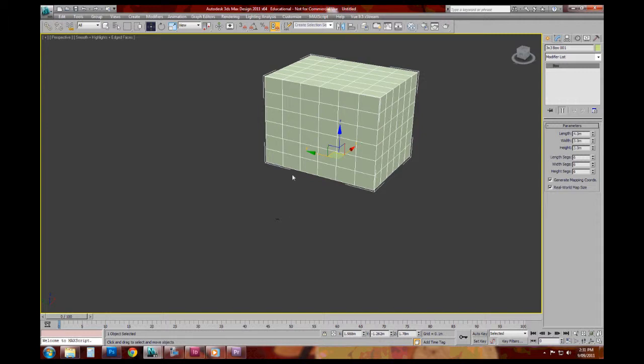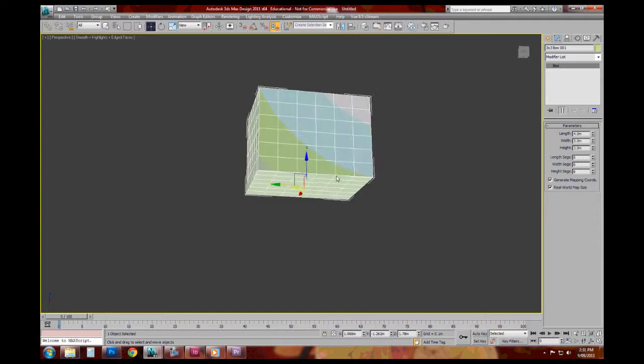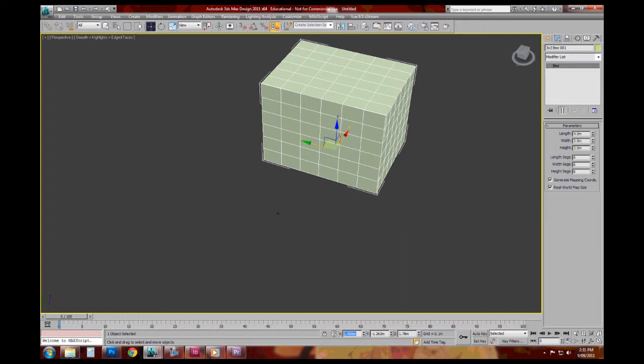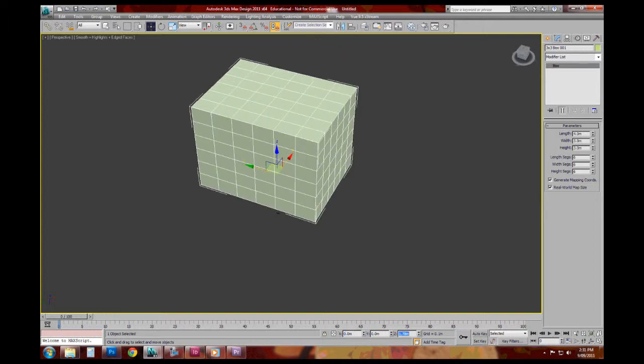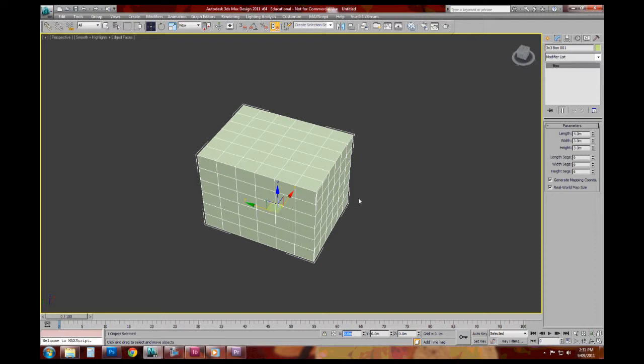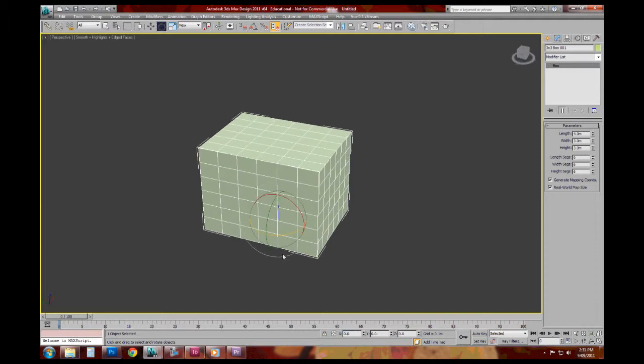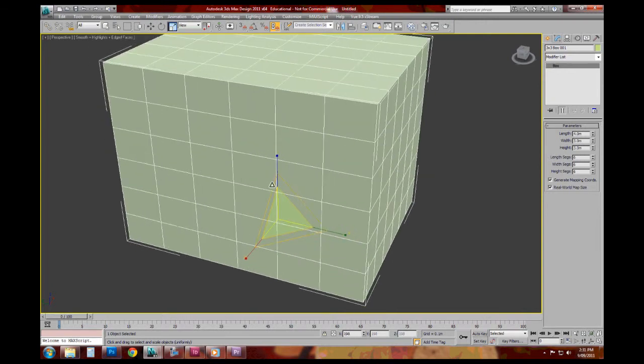And if you actually know the location that you want to put that box, that's where we can use this little world coordinate system input at the bottom. So I can drop that back to 0, 0, 0 just by writing 0, 0, 0 there. If I wanted to rotate the box, I can do so. And if I want to scale it, I can do that also.